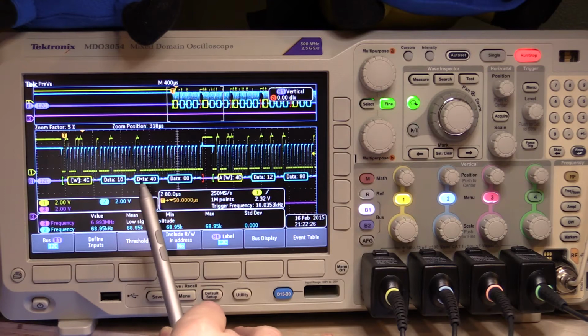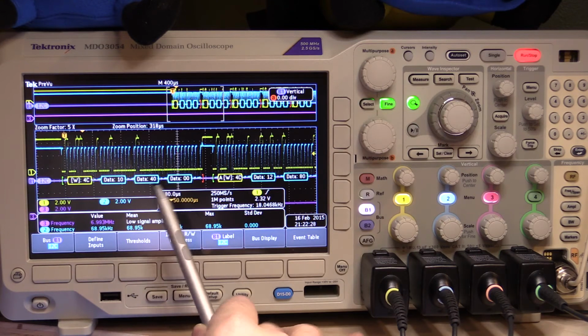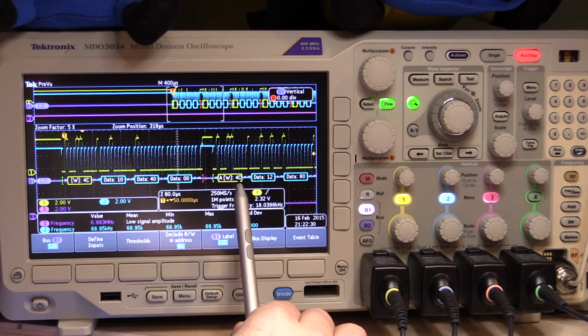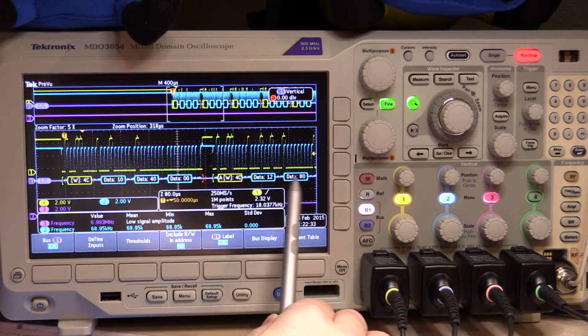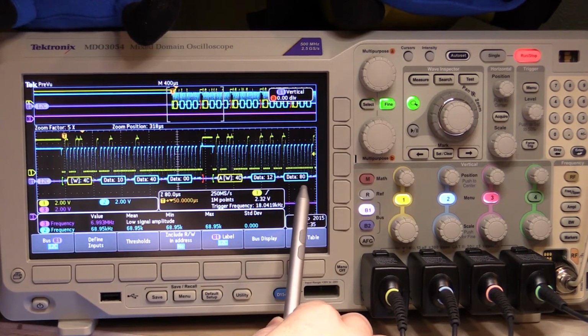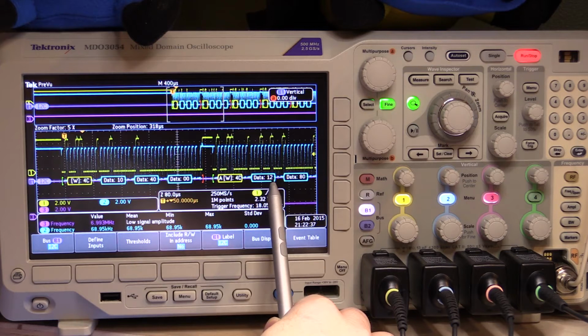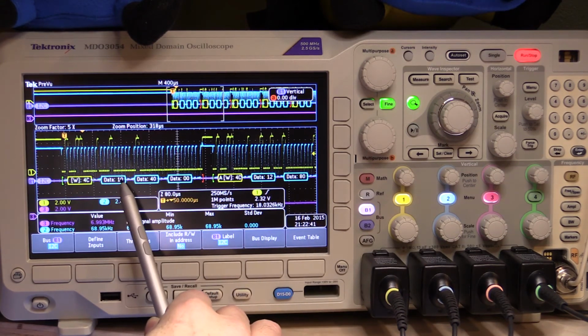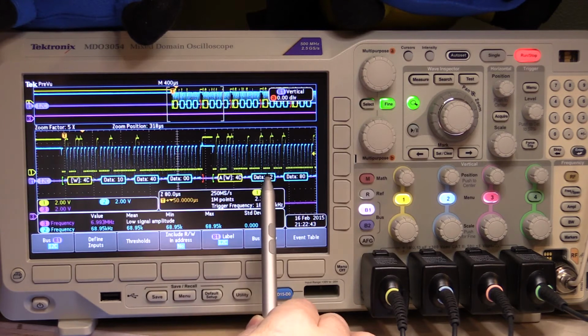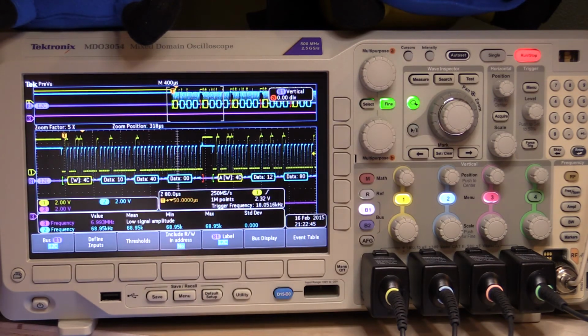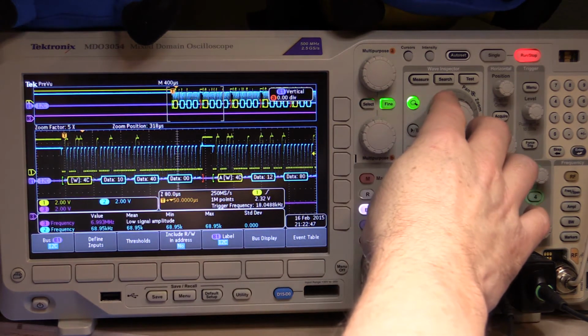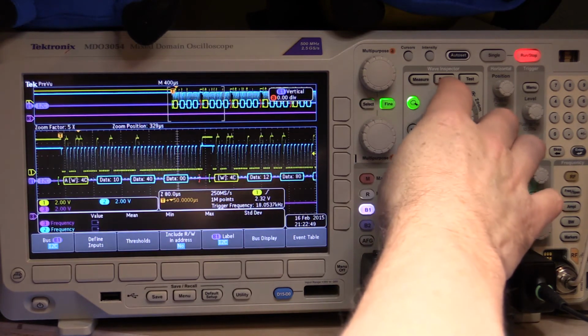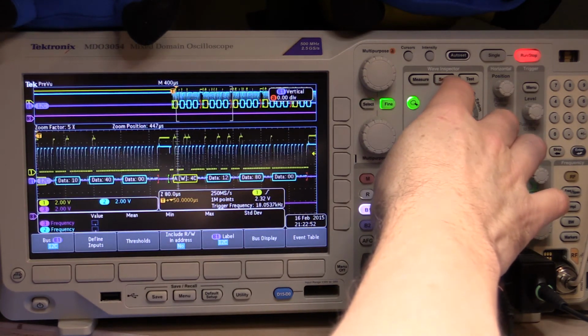We're sending out the 10, 40, and then we're sending out 4C again, which is the address again, and we're sending out a 12, which is addressing channel B. So the 10 was addressing channel A. This is addressing channel B with data 8, which is the halfway point. And if I just scroll across a little bit, you'll see that it's 80.